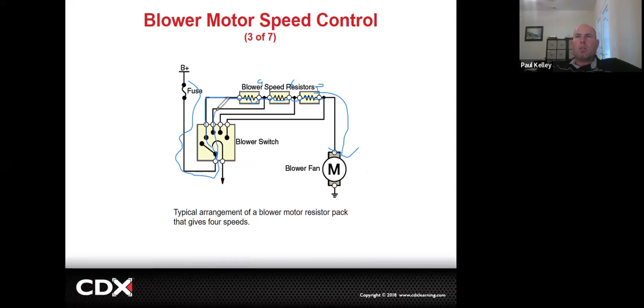Boom, we put on 2. Look, it starts with 12. So then it goes to 9. Then it goes to 6. So this thing gets 6 volts, still turning slow, but it's faster, right? So we put on 3. It goes to here, starts with 12, and it loses 3. So how many volts are coming out of that one on speed 3? 9 volts. Ooh, it speeds up.